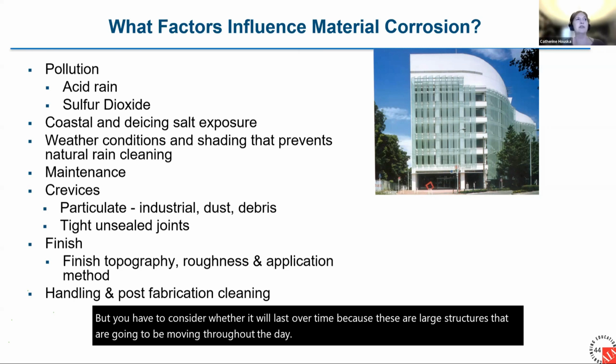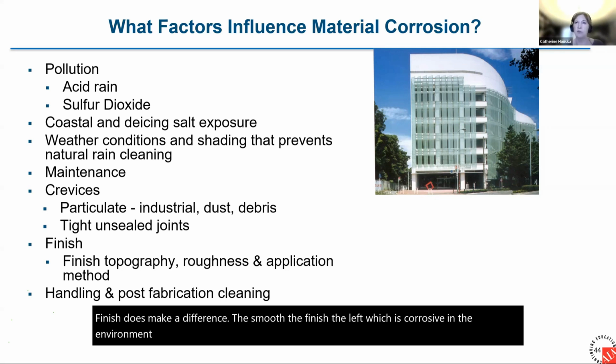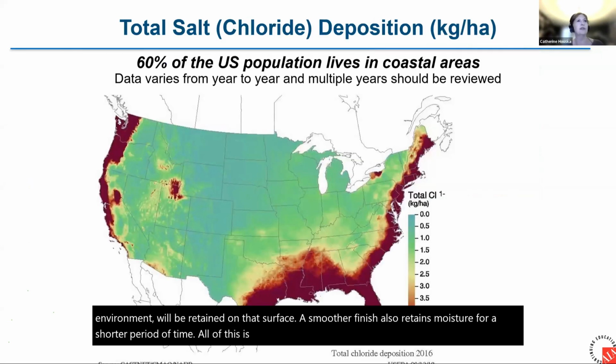Finish does make a difference. The smoother the finish, the less of what is corrosive in the environment will be retained on that surface. A smoother finish also retains moisture for a shorter period of time. All of this is important as you do an assessment.